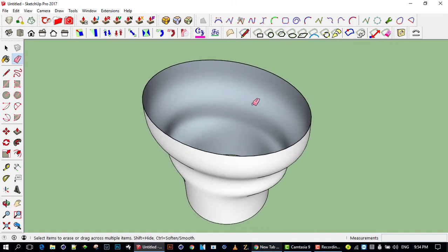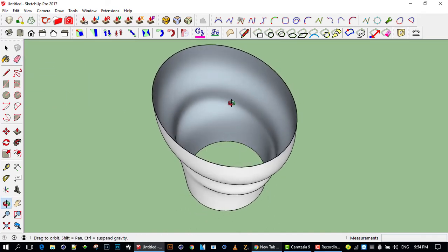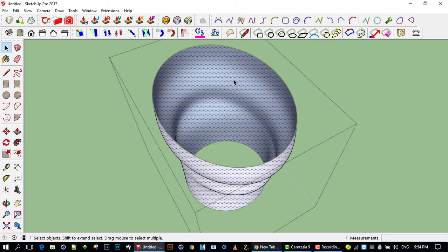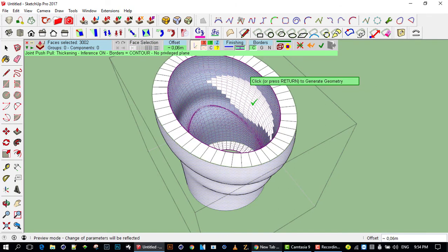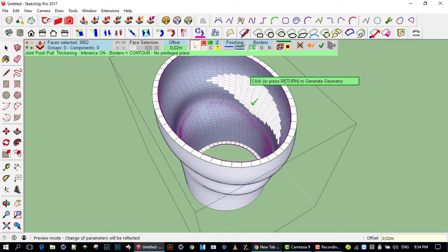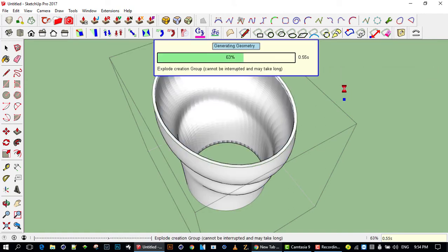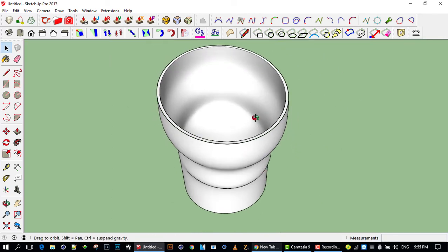Again, this will be transparent if we open it up in Unreal, and this will be visible. So I want to have a bit of thickness. So again, what we do is we select the surface and we go to the joint push and pull, and can you see it's got the plus there, so we will keep the original surface and create a second one. So we pull it in, and I'm going to say this is 2 centimeters, enter. Make it 1 centimeter, enter. If I'm happy with that kind of thickness, I click the button outside, and it's doing a bit of mathematics to calculate it, and that's where I'm pretty done.